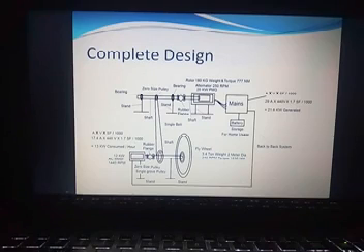Thereby, when we are rotating the flywheel, which is 3.4 tons with 240 RPM by a 12 kilowatt motor, the torque we are generating is 1250 Nm, and we are connecting this particular system to the alternator. The alternator is rotated very efficiently because of the ball bearings, which help the other side of the pulley rotate effortlessly.